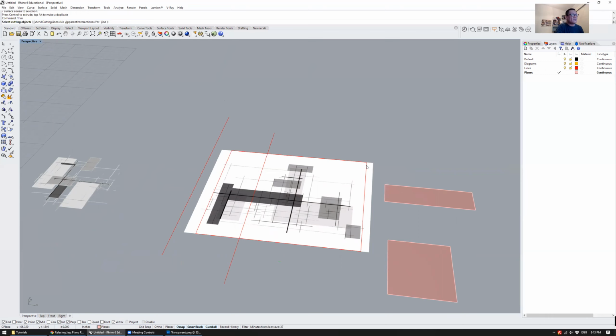When you have multiple things overlapping in the same place, it will ask you to select, and it will highlight so you can see which one. This is the curve that I'm selecting as the cutting object, enter, and then select object to trim. So I'll select the outsides of this diagram so I can trim it down to a perfect square.